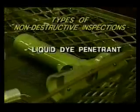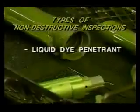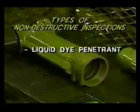The remaining NDI methods are only performed by qualified and certified NDI personnel. Each method has limitations and requires properly calibrated equipment. The liquid dye penetrant process can locate large stress corrosion or corrosion fatigue cracks on non-porous ferrous or non-ferrous metals. Dye is applied to the metal and enters the cracks. The dye is wiped off, and a developer is applied to the part which draws the dye to the surface.